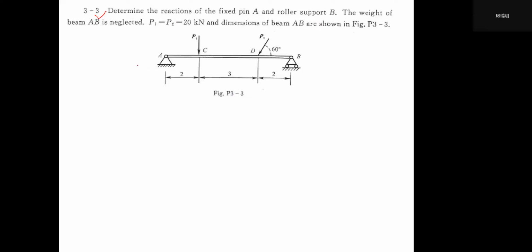So please, you guys, you can find it in the written position from our textbook, and you can try your best to finish. Just use 3 equations: sigma X equals 0, sigma Y equals 0, and sigma M about some point, maybe MA, equals 0, to find the reactions XA, YA, and YB, right?